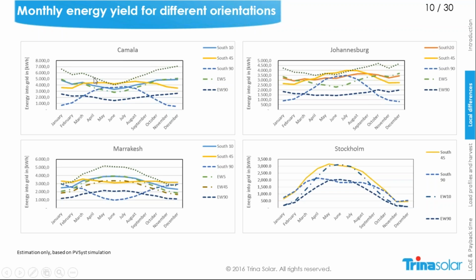here is the best one, for example in Calama, the tracker system, and you can see that, for example, in winter, the tracker system is on a similar level to a south-orientated system. But for sure, in the summer, when you have the highest irradiation, it's fairly better because you have a wider curve. That means you harvest more energy per day.